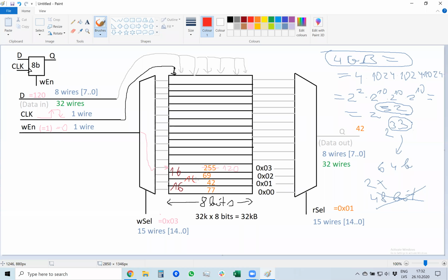So a 16-bit number stored in memory addresses that start with an odd number is impossible, because memory is just wired in this way. And 32-bit numbers must start at addresses that divide by 4. So for example, a 32-bit number can be stored in all these 4 memory addresses.